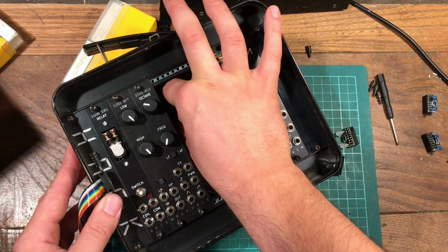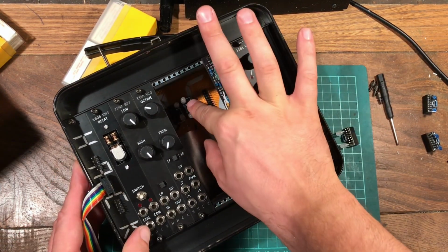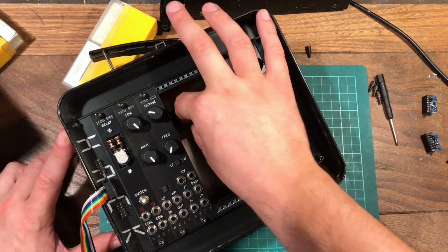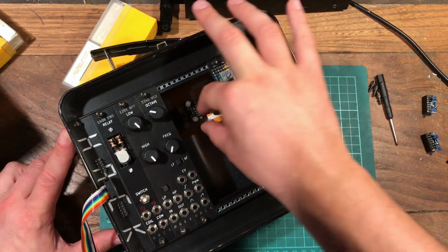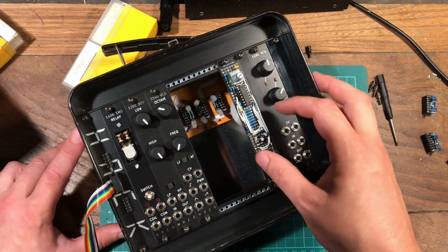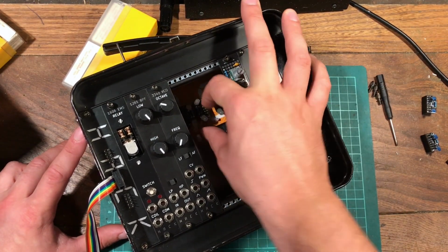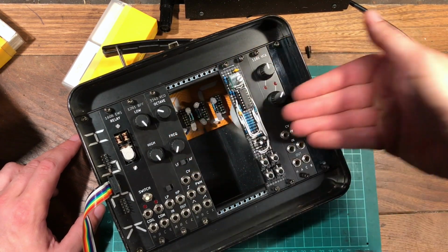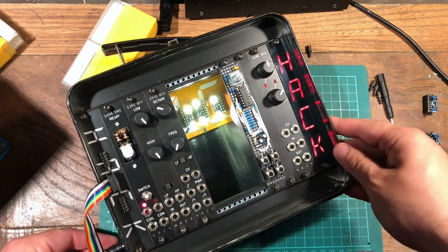So now let's put our little LED modules in, making sure that the stripe is pointing the right direction, and let's aim the LEDs around a bit to try and spread out the light. Very gently you can put them side to side as well as up and down. The ideal situation is that your power bus is midway on the case. Let's plug them in to test them.